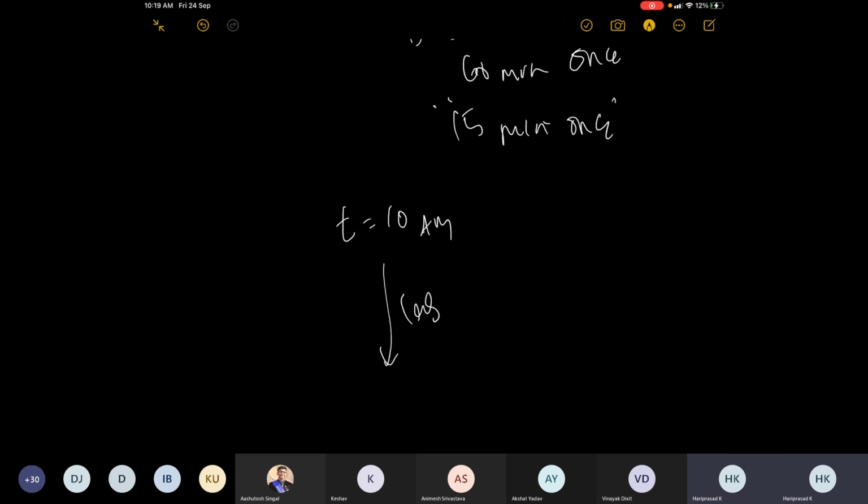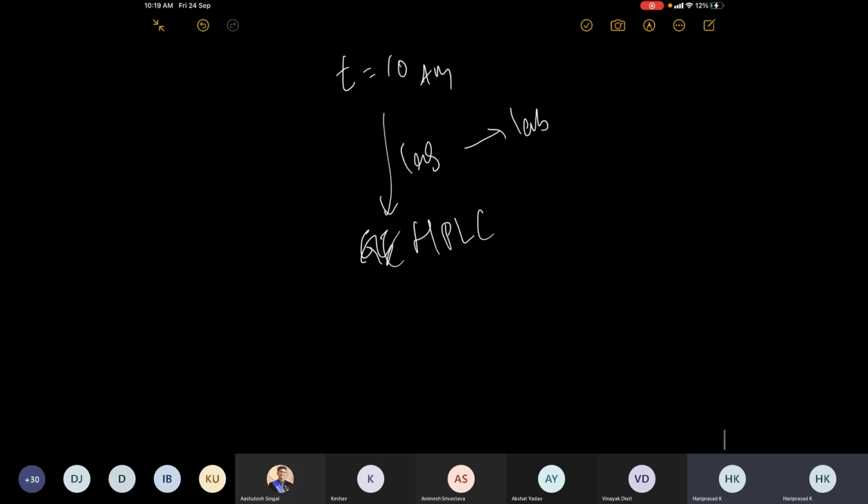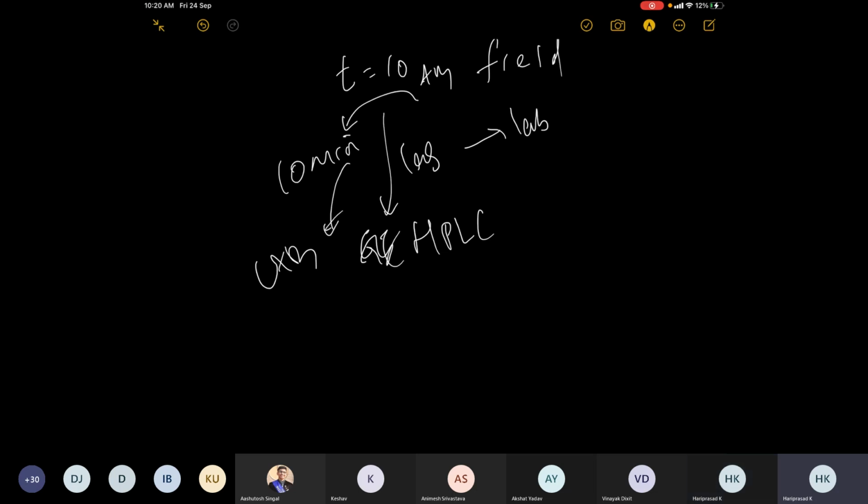There is a lag, because the sample has to be taken to the lab, and you have to run it in the instrument. GC is fairly fast, but for instance, with high performance liquid chromatography, you need to set up the sample and follow the protocol. Let's say the lab is somewhere at some corner of your plant, and the field maybe somewhere far away. Say it takes 10 minutes to bring the sample from the field to the lab, and operation of the HPLC may also take around 10 minutes.